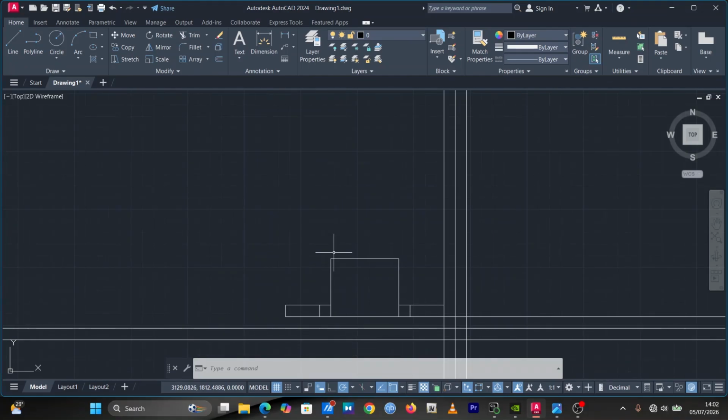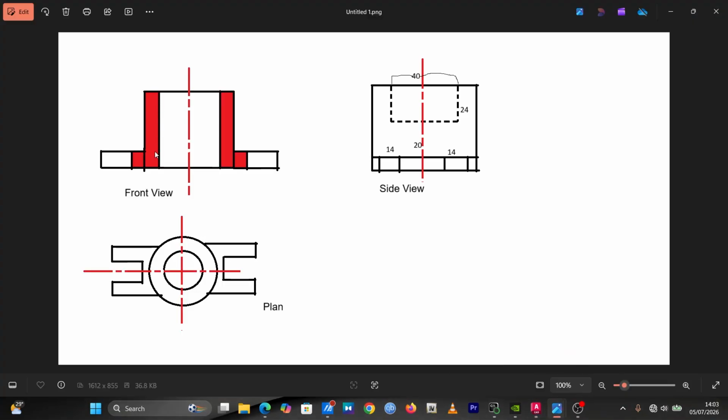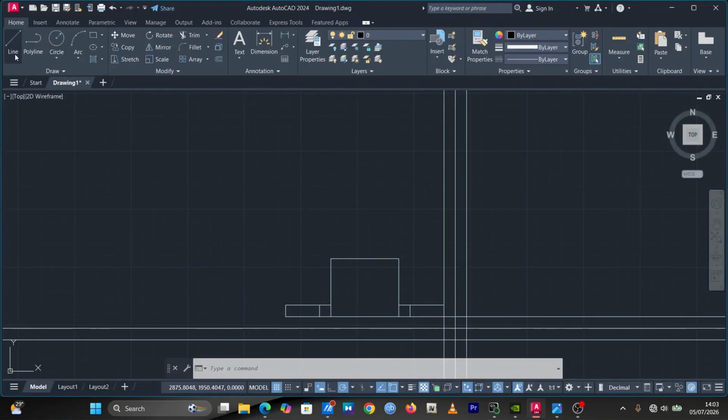So from here, we are also going to draw this side, this cutting line over here. So from here to here is 10, and then from here to here is also 10. So we do that. Pick our line to stand here, measure a distance of 10. Cut, you pick your line again. Stand here, measure a distance of 10. And then you cut. Now you draw your straight line to cut through it.